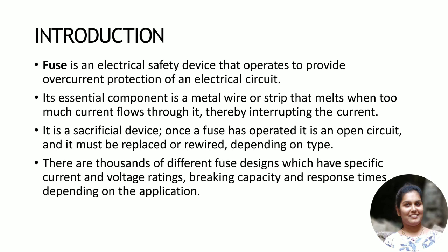Once the fuse is blown out, it should be either replaced or rewired depending upon the type of the fuse used in that application. There are thousands and thousands of different fuse devices which have specific current and voltage rating, breaking capability and response time depending upon the application.